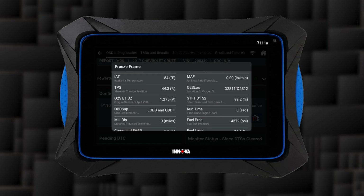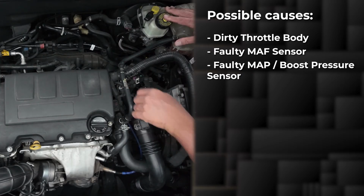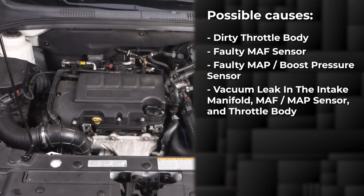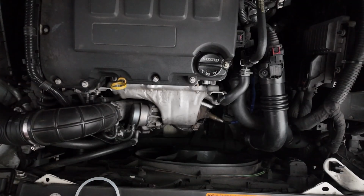Now, let's take a closer look at what could be causing this code. With code P1101, there are several possible causes, including a dirty throttle body, a faulty MAP sensor, a faulty MAP boost pressure sensor, a vacuum leak in the intake manifold, MAP sensor, or throttle body, and a plugged PCV system. There's a lot of things that could be wrong. So first we need to run a few tests to figure out exactly what's causing this code. Let's go step by step.